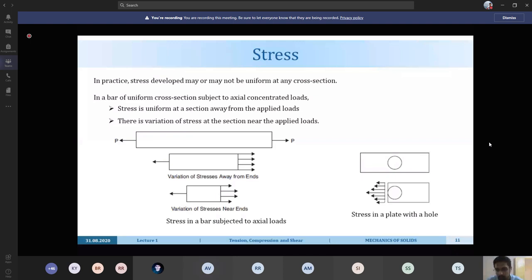So, sir, can we say that removing material causes less stress to develop at that point, because the restoring-force-causing material has been removed? Yes, that is true. That's why, when you put a screw, I have an example later. When you drill a hole in the plate, you should check the shear stress, whether that plate can hold with that drilled part.